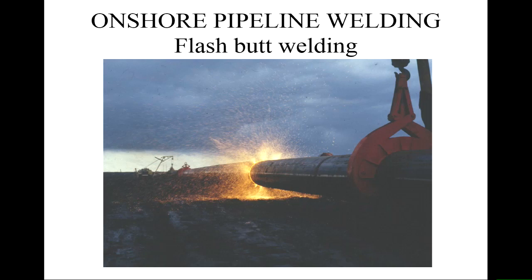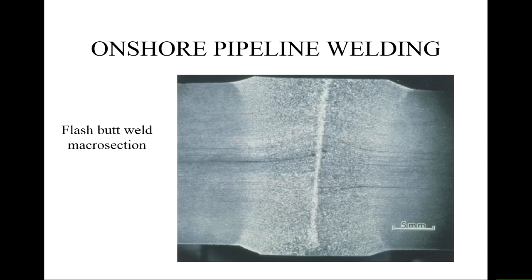But it's a nice one-shot process. And then the clamp basically contracts and pulls the things together at the end of the process. So you end up with a weld that looks like this. So this is the original line where the metal is there. And you can see the rolled steel microstructure in. You squeeze it together and the material squeezes out sideways and upwards.